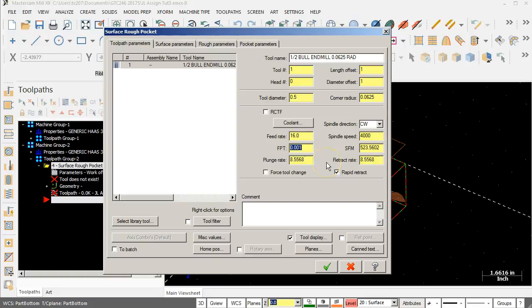It is on this machine, light duty machine, I don't want to push it too hard. On the roughing passes for the other piece, we were able to double that, go up to 32 inches a minute until the very last passes. And when it got to the last passes and the helical entry or the starting off of the part was not able to be calculated, then it went over to plunge, and then I really wanted it to plunge at 8, not at 16 or 32.